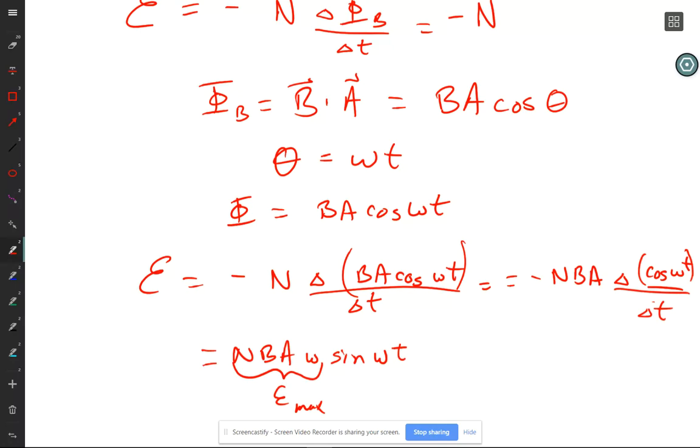So somebody realized along the way, wait a minute, I have a generator here. The generator is connected to the engine already, right? Because it's running off the engine. If I just take that generator and I force electricity through it, it becomes a motor. And so instead of going out there and cranking, I can just have some wiring set up so that, instead of charging the battery from the generator, I will turn over the engine using energy from the battery. And so they use the generators to start it. Genius, right?